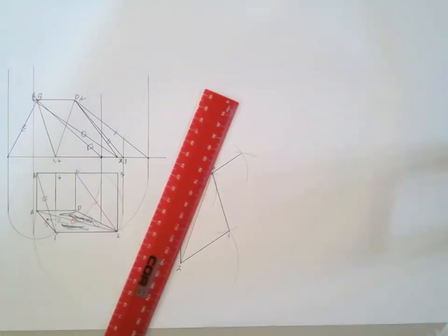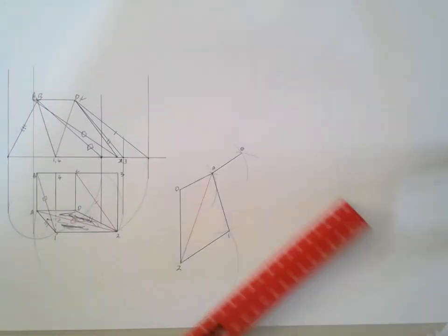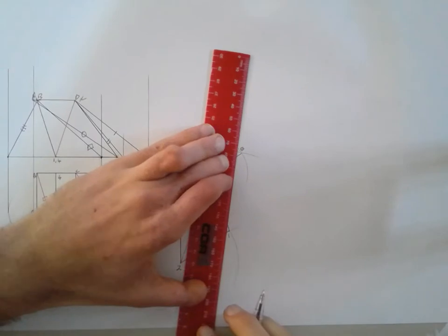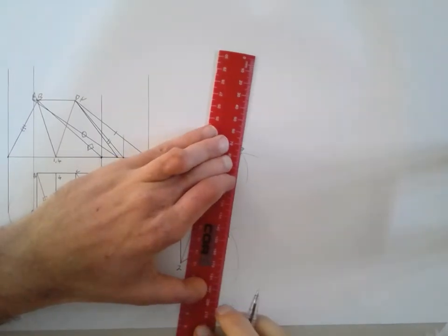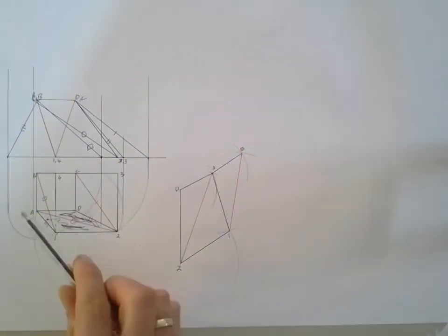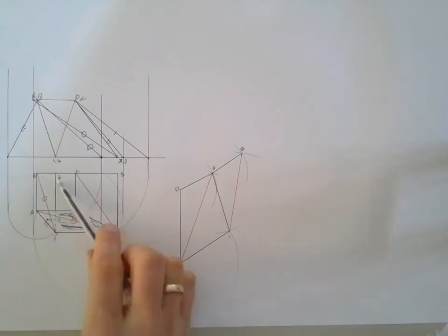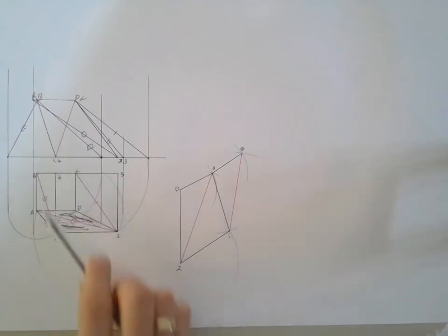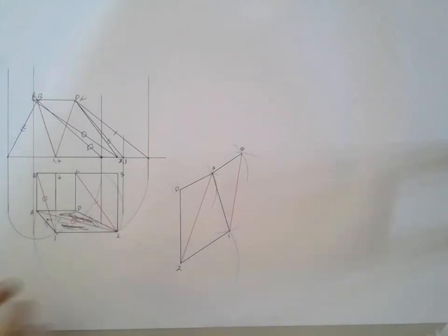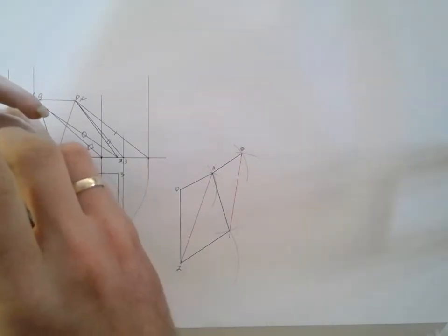And that will, of course, be point B now. And then I need a construction line from B to 1, because it's again another line that you drew in to triangulate. And that's now completed that triangle from A to B to 1. Then I need this triangle here, which is triangle B1 and point 4. So I need the true length of line 1 to 4, which is already here in the top view.